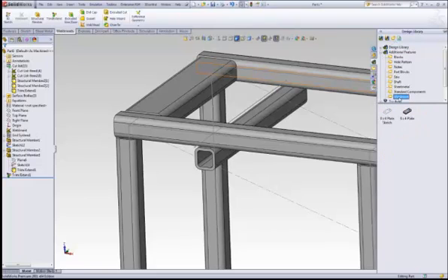See, I've got a weldment folder over here, and I just added one for the sake of this presentation. You could do a 2D sketch, or you could do a 3D model. I think I would recommend doing 2D sketches when you drag and drop these in, because the 3D model tends to leave the merge result checkbox on, even though we're creating a weldment. You could also drag and drop in parts if you want that are derived components. So if you change that part, it will change it in any other weldment that it's being used in.